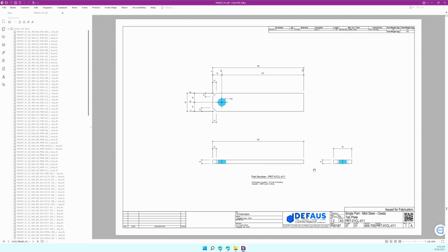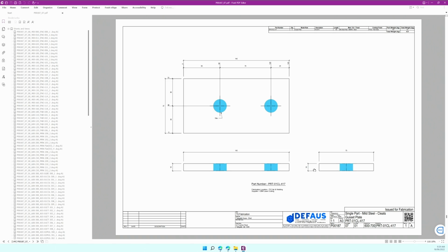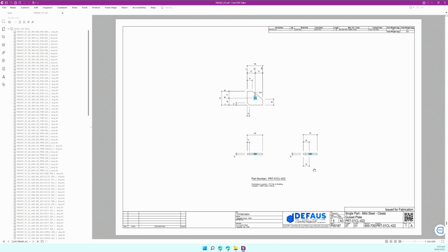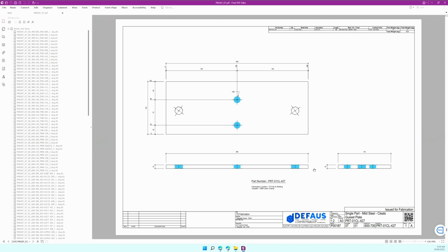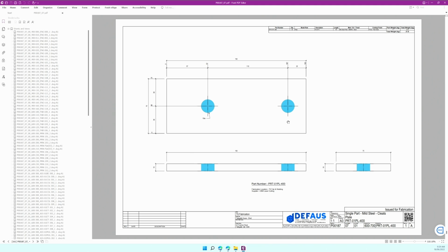So there are cleat drawings. Oh, there we go. So these holes here should be blue like the rest of them. I would say there is an issue with a bolt, or how that is actually modelled. I'd go back and look at that. I think there's something modelled slightly incorrectly. I would say maybe the bolt is slightly skew-if on that particular connection.